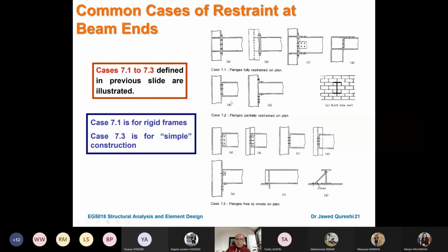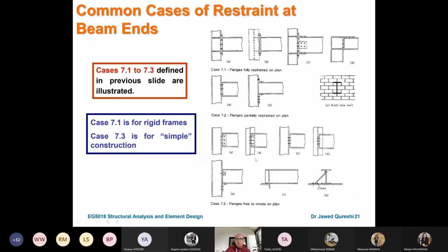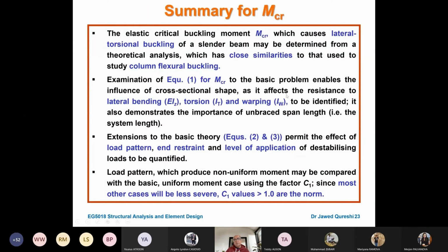And then we have semi-rigid connections. The typical examples are if we have a full depth end plate, so LCR is equal to 0.8 times L. Finally, we have web cleats bolted to the beam and then again bolted to the column. Now, one thing that we avoid in case of unrestrained beams is the fin plate connection. Fin plate connection means that you weld a plate to the column and then you bolt it to the beam, because it does not provide much torsional rigidity. The most common simple connections are partial depth end plate connections. So the most common one, if you're not sure, then it is LCR equal to 1 times L. This is a summary of MCR.